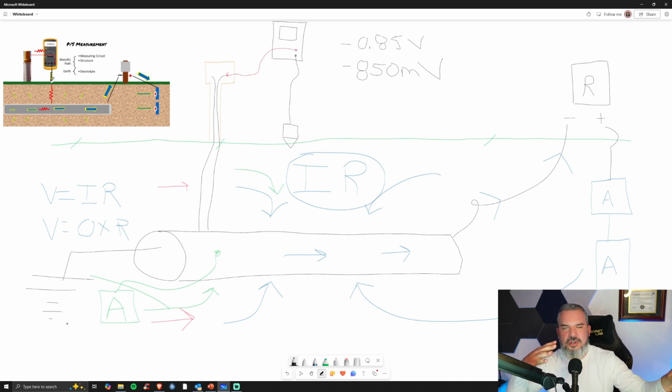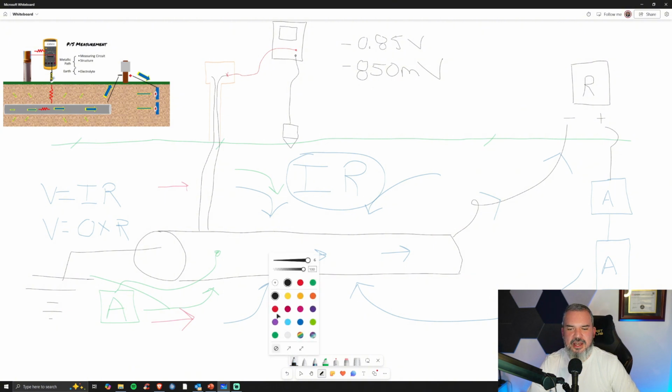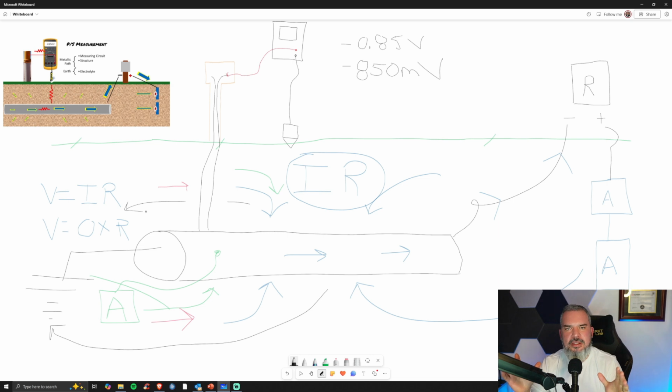If I'm shorted to a copper station, my steel pipeline may corrode to protect my copper, which produces, we'll just call that black current, back to the grounding, which means I'm going to have error in my reading there too. So I'm overcomplicating this on purpose, but this is really reality. There's a lot of folks out there going through this. They're feeling this pain, and they're like, how in that simple pipe to soil potential, gosh, man, it just became not simple. What do I do?